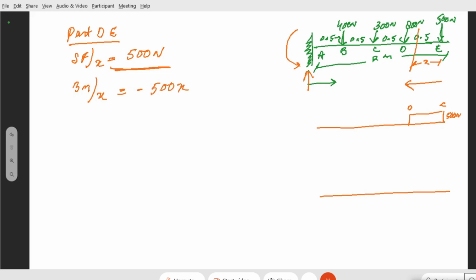Now, I have to calculate different values at different points. I have 2 points. Point 1 is when X is equal to 0. That means which point? Point E. Giving the value of bending moment at E, that will be equal to 0. That means at point E it is simply 0, and the direction would be negative. Sorry, here it is E. Bending moment at E is 0.